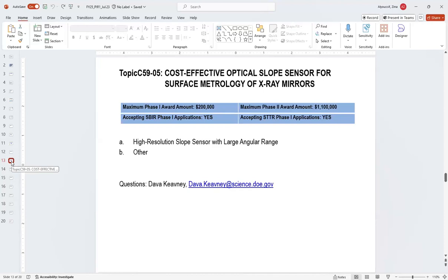This is essentially a new type of autocollimator made here in the US, not by international vendors, which have many performance limitations, especially for applications extended beyond mirrors to include gratings, glazed or lamellar ones. The performance specifications are listed. Just a few of them I'll mention here. Again, this is 25 nanoradian RMS and then 15 milliradian angular range.